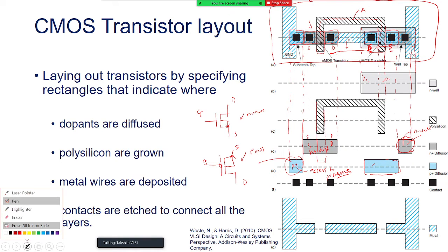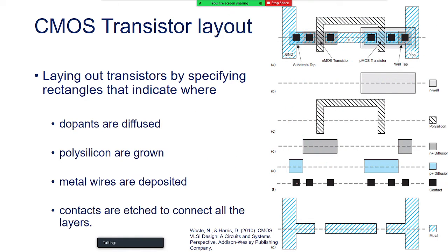So I am just going to erase this all. So what I want now, access to this, I want wires to connect to each of these terminals, just like you create a circuit on a breadboard or PCB. So I define these contacts in the areas I fabricated. So you see now these contacts are here. Basically they are giving me access to connect to the source and the drains, again source and the drains, and the body of those transistors as well.